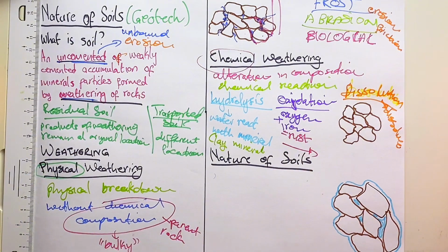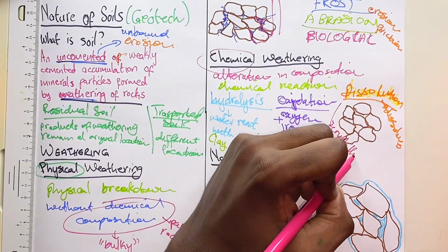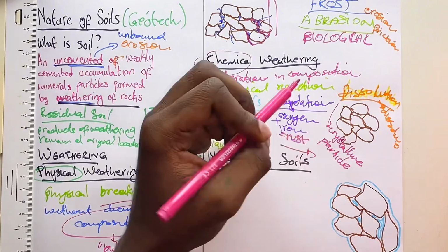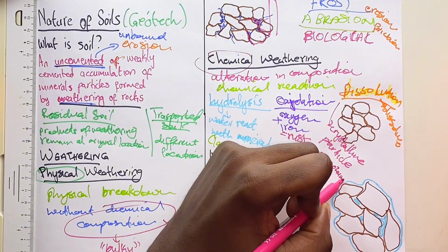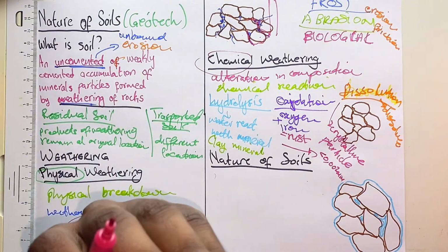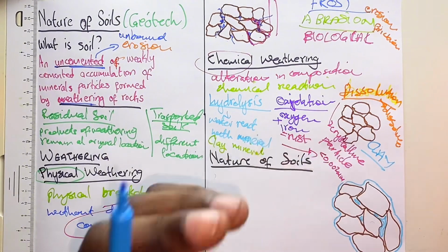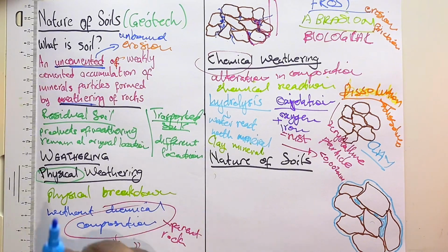Now, in dissolution, when your particles react and dissolve, they will form some crystalline particles that are smaller than 0.02 millimeters. They are so small and so wet because they are dissolved, mixing with water, and that is exactly the composition of what we call clay. Your clay is a result of your soil or rock being mixed with water, and the minerals in it that have the ability to be dissolved will be dissolved to form a crystalline particle. The interesting thing about clay is that the soil doesn't actually react with the water, it just mixes with it.